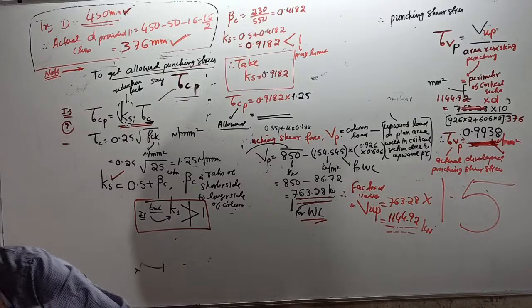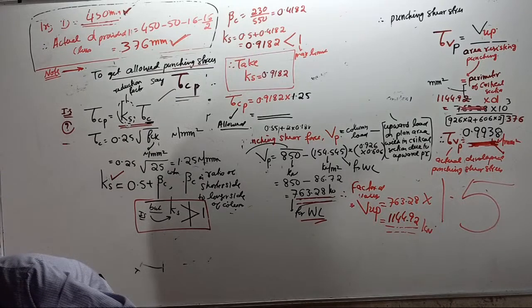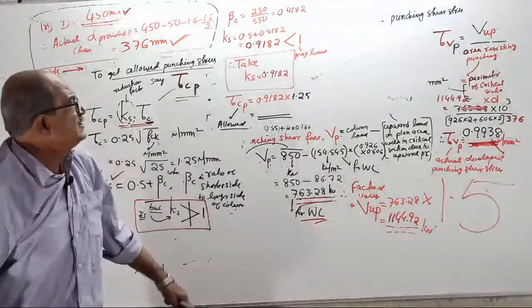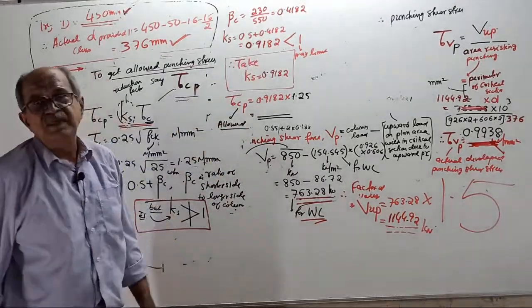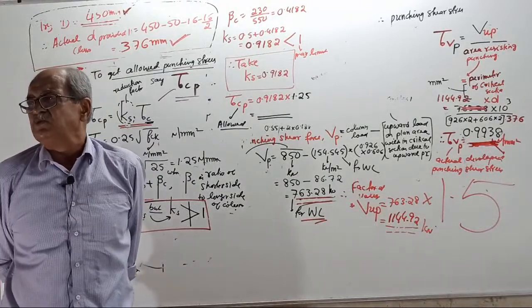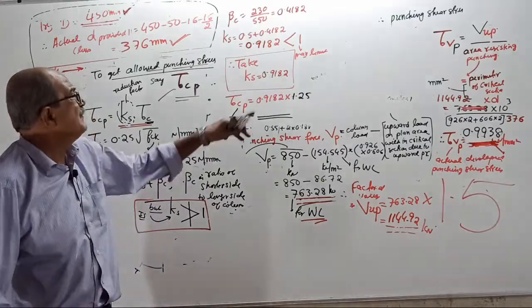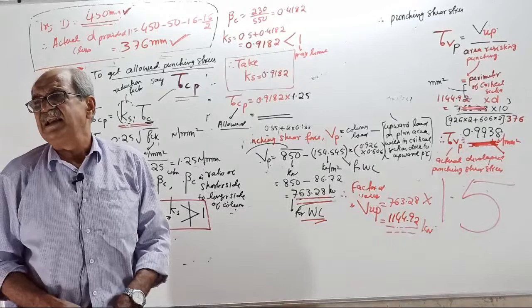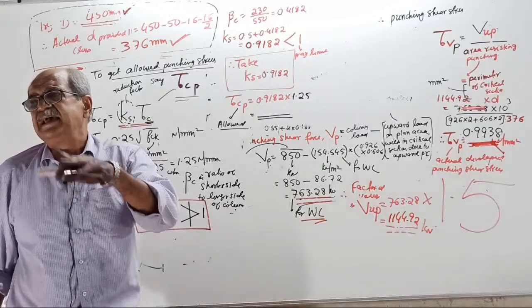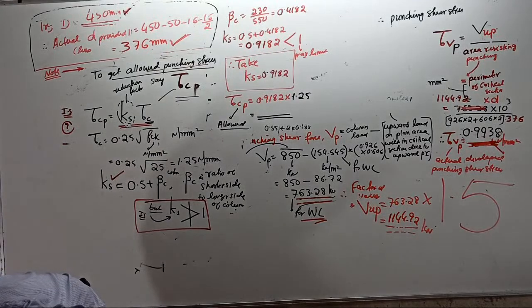No. The IS code has not, yes, you calculate, it will come 1.5. So reduction is not there. I told it 10 times. If it is square also, the IS code gave the same formula. Your ratio will come 1. When the ratio comes 1, 0.5 plus 1 will come 1.5. Therefore the reduction is not applicable. They gave a general formula. Instead of wasting time on explanation, they decided on a common formula which will take care of everything.